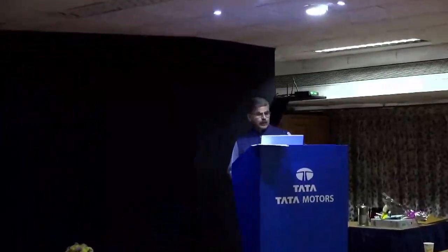Then there are some new materials like Cronidur, also referred to as Nitromax, VC444, and 444. They are being used presently, and they are replacing 52100, M50, 440C, BG42, and Chromex 40 materials. And in some applications, they told us that some of the rings can also be made using Inconel 718 material.